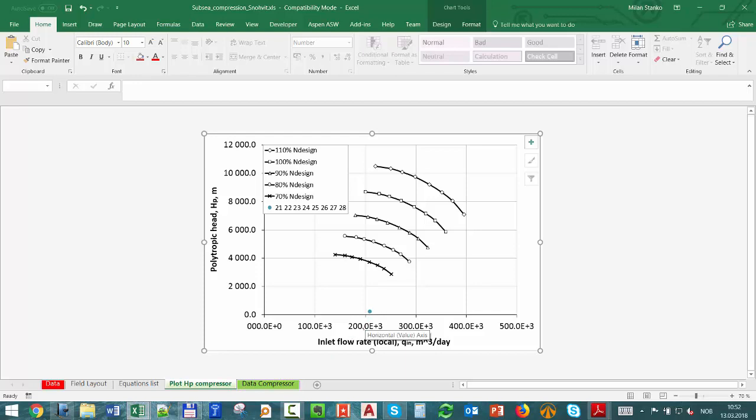Then I go here, and actually, that's my point. Conclusion: it doesn't look fine, right? I cannot operate because here will be my minimum rotational speed, that will be the maximum, and the point falls way below. So does it mean I cannot use this compressor for this application? Remember, we are now just in the first year. In the first year, we shouldn't have a big difference in pressure. So maybe the compressor will work because later the pressure ratio will increase, and that will tend to move the point upwards. So we should not just discard that option initially.